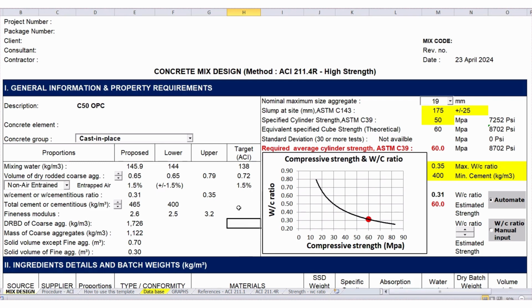So let me explain further. Let's say, Cesar, my result is always plus 3 MPa from the template that you provided me. So it's very easy. We don't need to complicate the matter. Simply add 3 MPa in this formula. So every time you use this formula, it's more than 3 MPa. So again, it will equate to whatever you're experiencing in your plant, in your own degree of quality control. Let me go back to the previous formula.